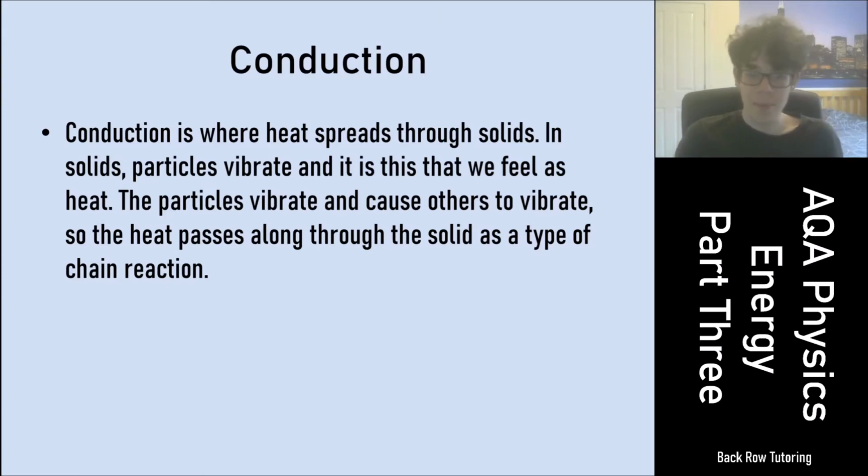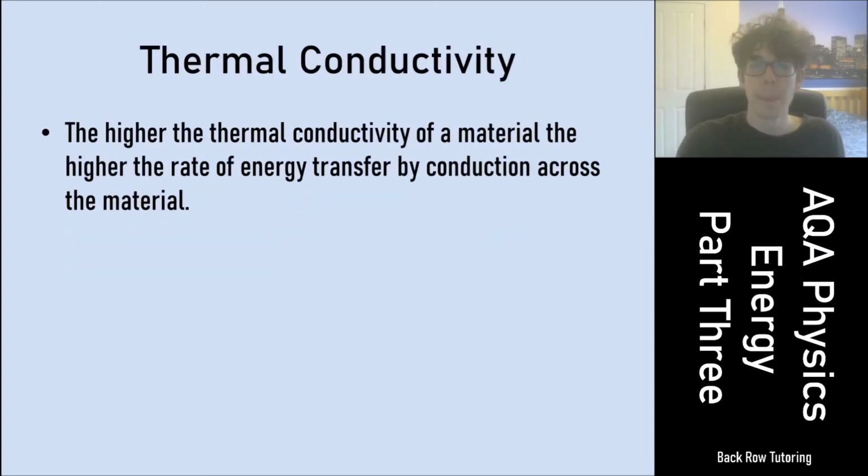These particles are vibrating, and these cause chain reactions, so the heat spreads through the medium. The higher the thermal conductivity of a material, the higher the rate of energy transfer by conduction across the material. So if you have a material with a high thermal conductivity, then the energy transfer through heat will be quick. It'll travel through that material quickly.